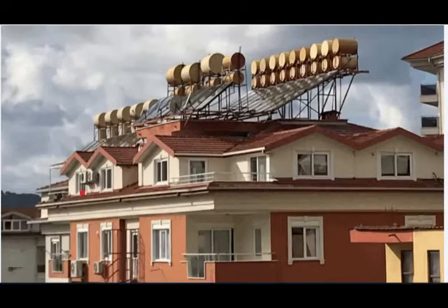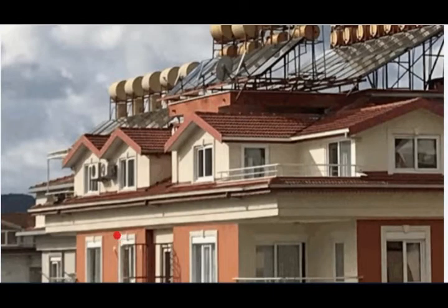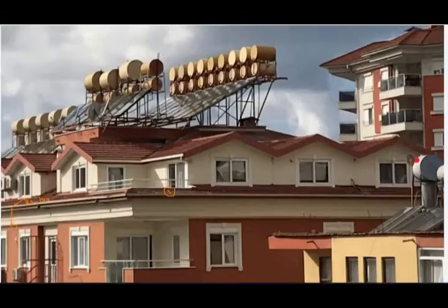Again, look here. We can easily understand completely. He did an 80 centimeter console, even maybe less, 80 centimeter up, and from here they did a slope. And this slope, according to the rule, should not be less than 30 centimeter. You can do it 1 meter, it doesn't matter, but it should not be less than 30 centimeter. As you can see here, this slope is good. The municipality is saying that we should see the roof here. So this is the symbol of the roof, which is continuing here.